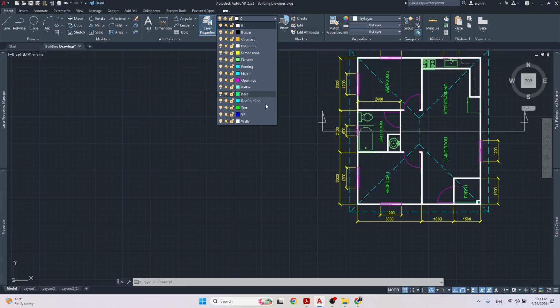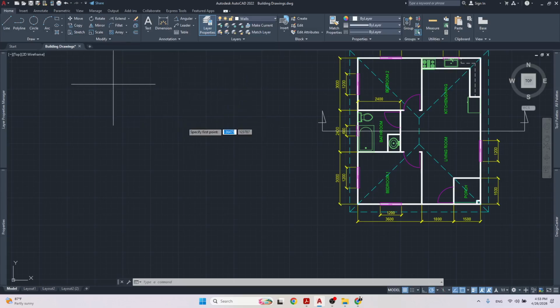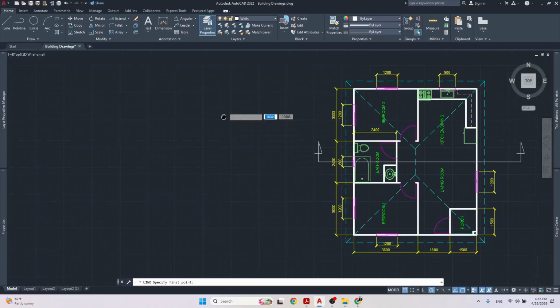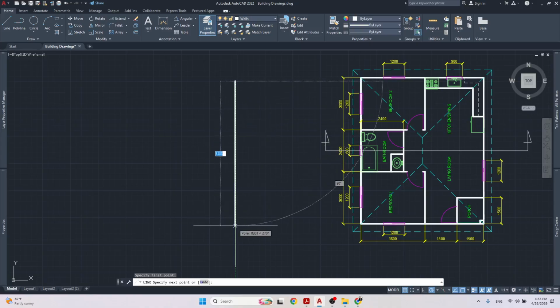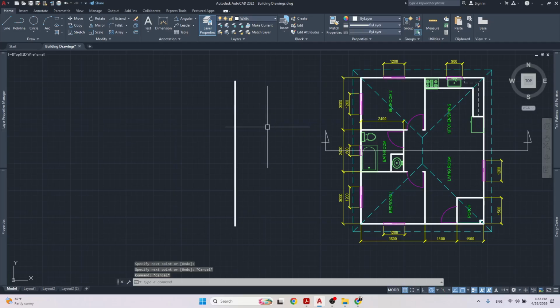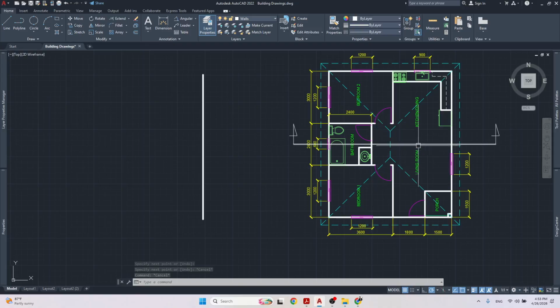Okay, so let's start. Let's go to the wall layer, and let's start with some lines. These lines are not going to be any particular length as yet. We can cut them off after. This is going to be a wall, because remember, we're cutting through the roof down to the walls, down to the floor, into the foundation. I'm going to be drawing starting from this side first, coming across from right to left.